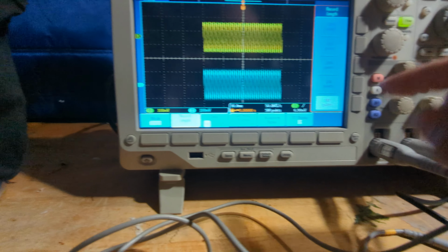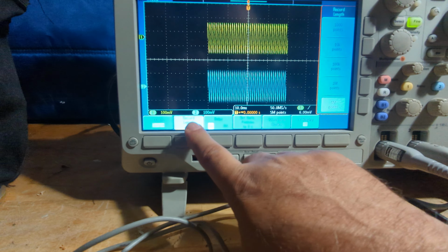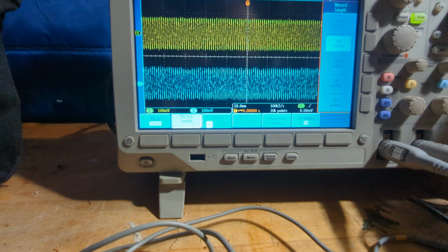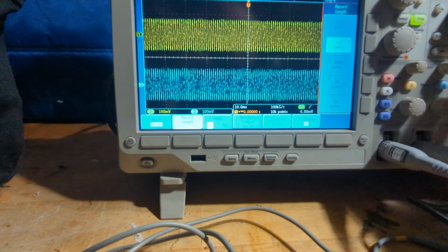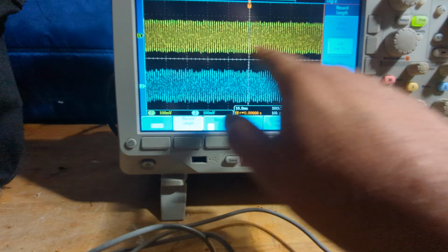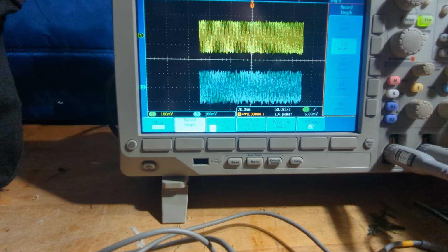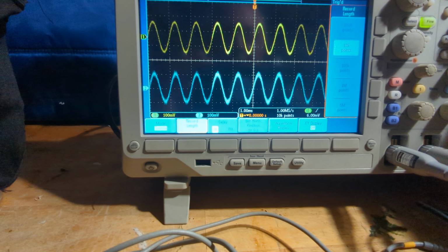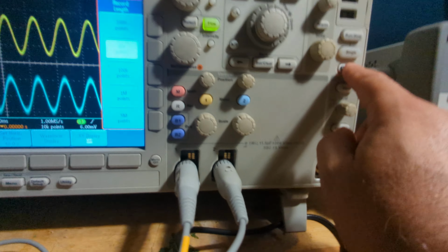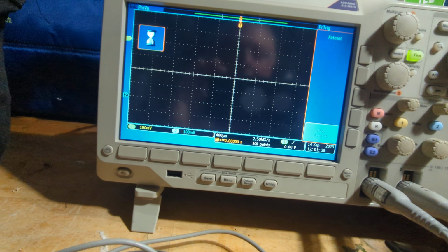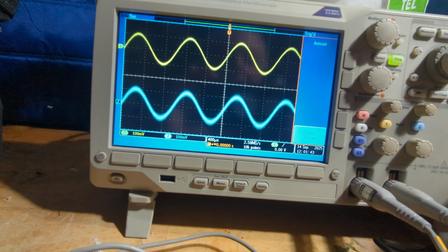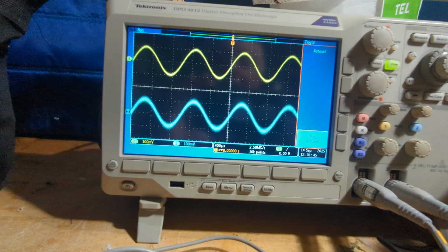So we'll go back. That takes data, so we'll go back to 10K, and then we'll run stop. All right, now I'm zoomed out. Right, my x-axis time is not as accurate. All right, and if you mess up, there's something called auto set, and it'll bring everything back. All right.